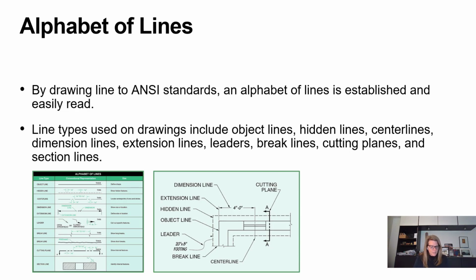The dimension lines are what are dimensioning whatever feature it is you're trying to describe. So in this case, at the bottom you have the face of the building and the dimension to the center line of the window. You see that center line denoted here, and the dimension is here. Now, there are lots of ways in which you can describe dimensions, as you will see later on. There's the extension line that, again, is denoting one point of that dimension and the other point.